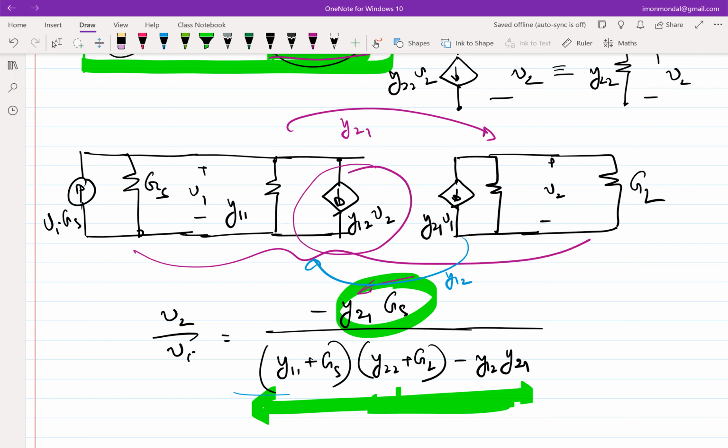Because in what I have done here, I told you that all these terms are frequency independent. But it did not necessarily need to be the case. I started off with frequency independence, all these real, because it helps make the point. But in a real system, none of these are frequency independent. All of these terms are frequency dependent. So this denominator will be set to 0 at maybe a certain range of frequencies, or a single frequency, or a set of frequencies. When your denominator gets set to 0 at, let's say, a single frequency, then the oscillation will happen at that frequency. And that frequency is a function of how the system has been made.